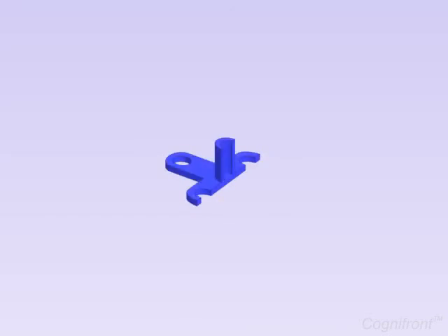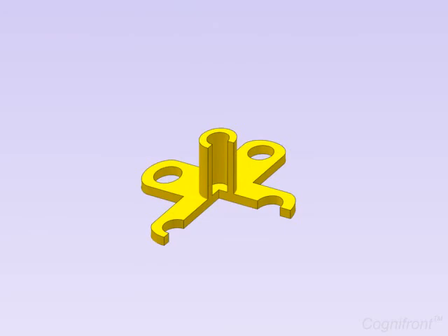Then, a half sectional view illustrates both the outside and inside views of the object in a single view. In this, only one half of the symmetrical object is cut, exposing the interior features of the object. Then, the uncut half can be drawn highlighting the external view.